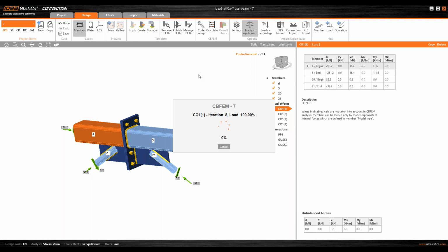It's a nonlinear calculation because we consider an ideal elastoplastic diagram of the material with a maximum of 5% of plastic redistribution or plastic strain. It's according to code.